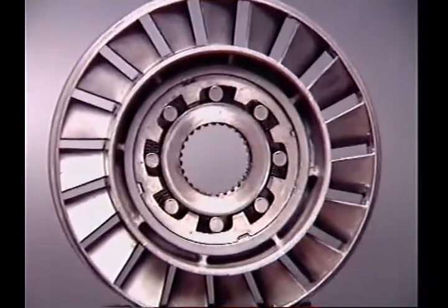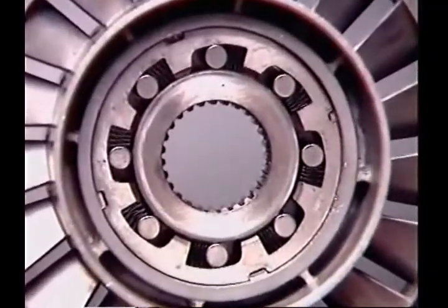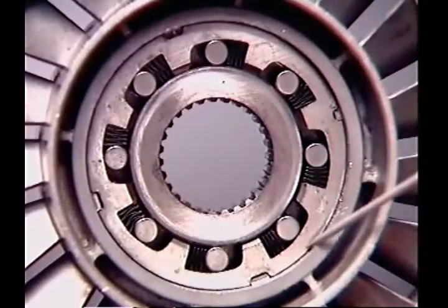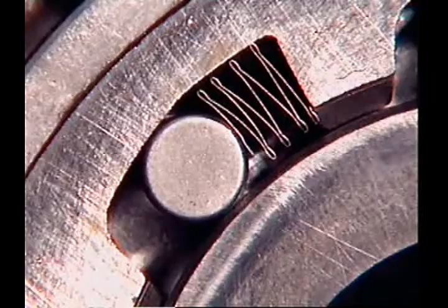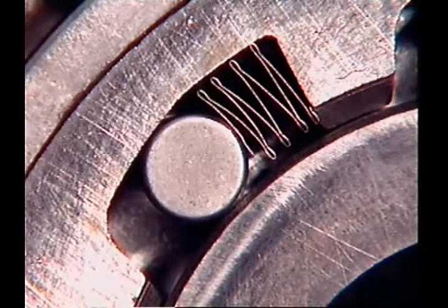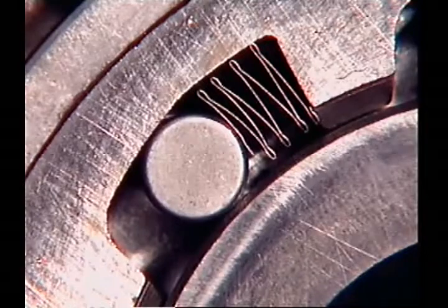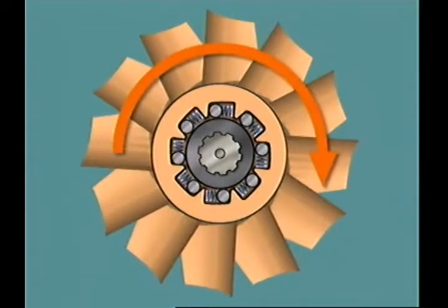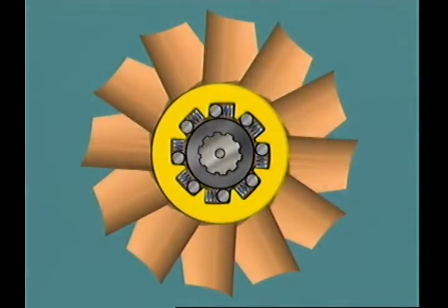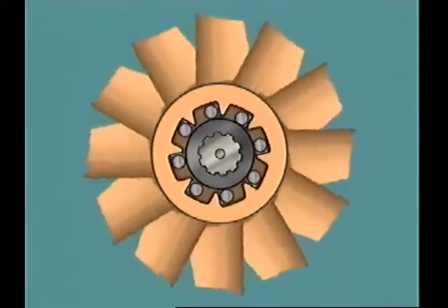In the roller type one-way clutch, the inner race is splined to the stator support. The outer race has wedge-shaped segments which retain the rollers. In each segment, a waved compression spring pushes each roller towards the narrow end of the wedge. A force on the stator blades against engine rotation locks the outer race onto the rollers, wedged between the two races. Turning the stator with the engine rotation eases the wedging, and the stator rotates with the impeller and turbine.